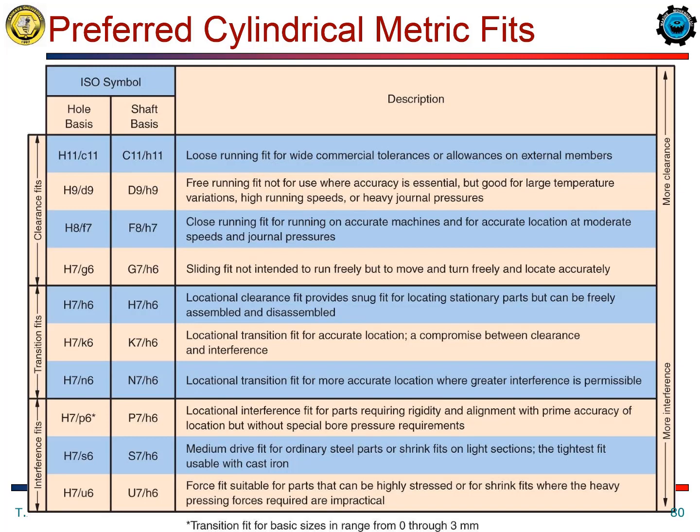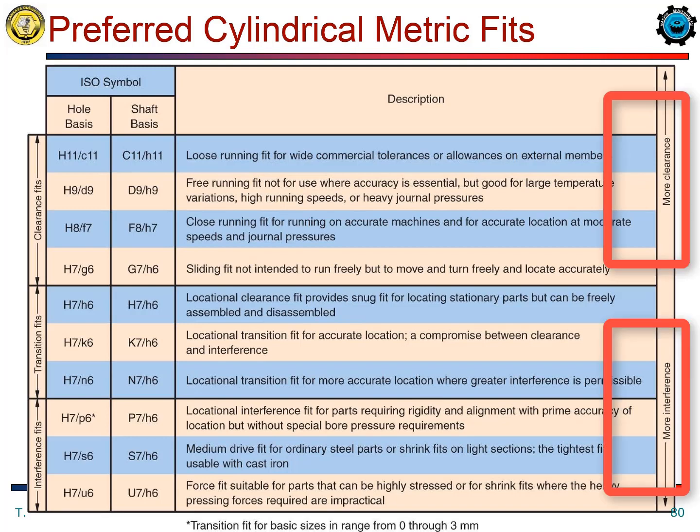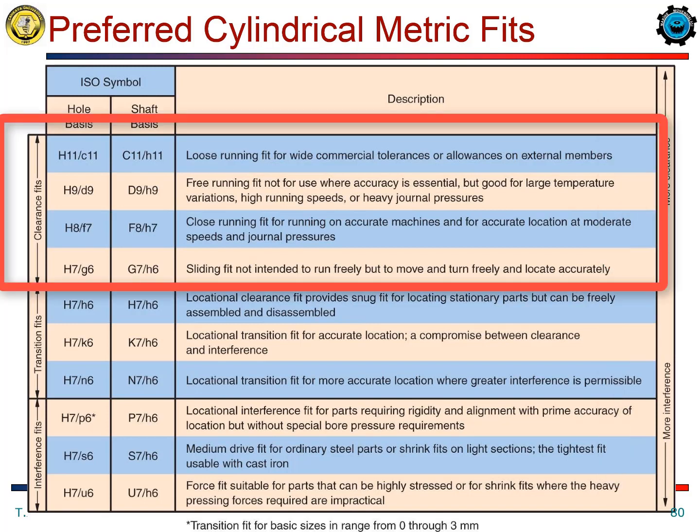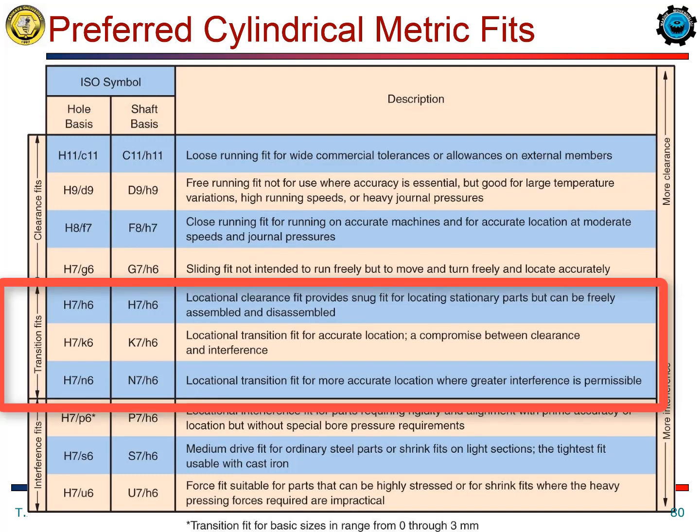In this table, the loosest fit is on the top side and the tightest fit is on the bottom side. In the table, the first 3 rows are used for clearance fit connections. The 3 rows in the middle are used for transition fit tolerances.